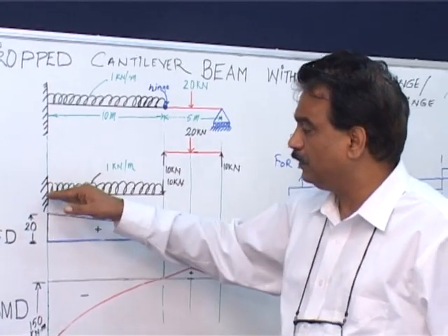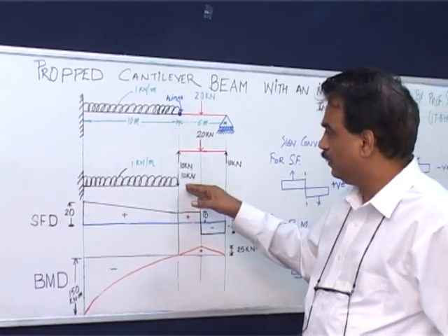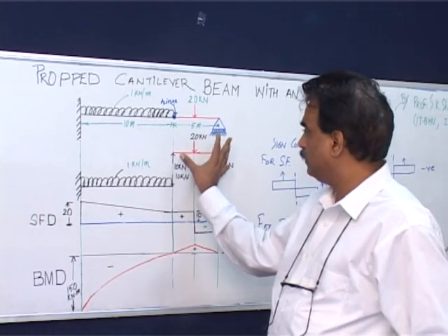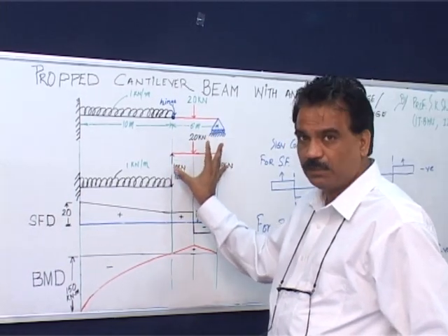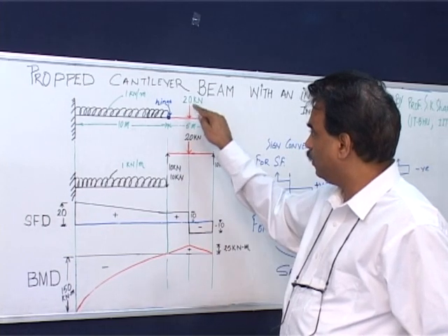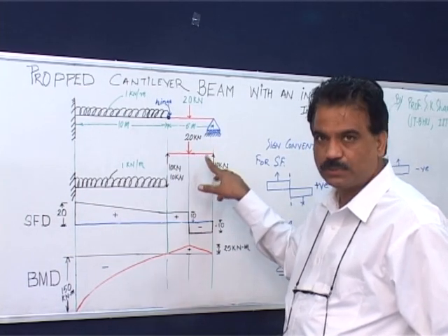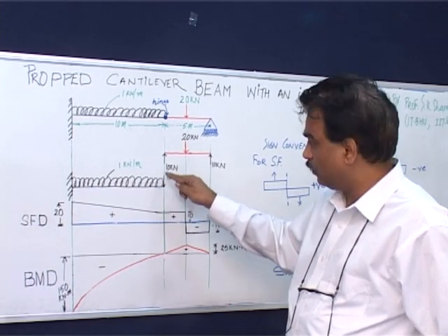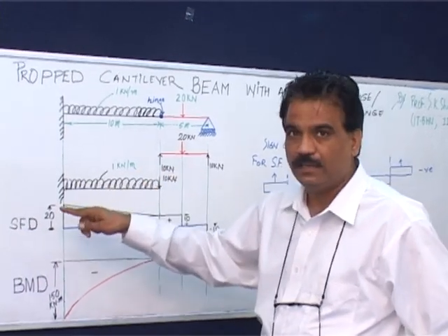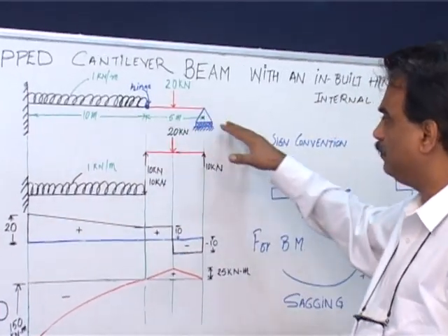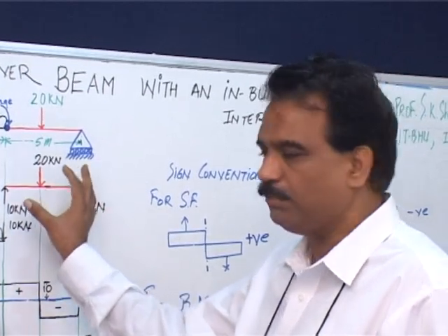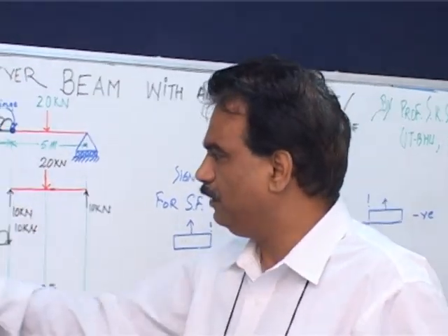And in the rest of the beam, you already have a UDL. So this bigger problem gets resolved into 2 parts. One is a simply supported beam having a load in the middle and supports at the 2 ends, and second, a concentrated load at one end, and then a UDL. Now how do you solve it? This bigger problem now gets resolved into 2 smaller problems: a simply supported beam and a beam with a UDL.